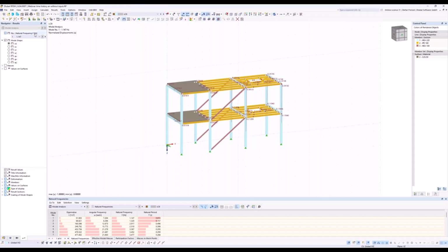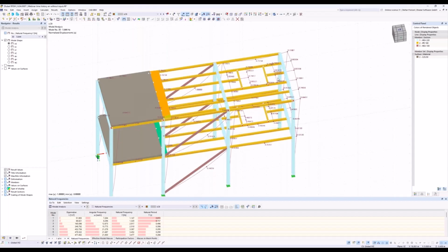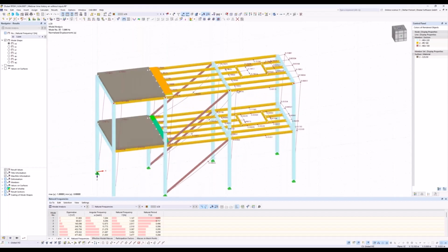So our first natural frequency you can find here in the navigator, or the result navigator. Here, of course, you can switch to the eigenvalues. And here is a really interesting eigenvalue. It's also 5.6 hertz, like our induced vibration, and you can see the structure will move in x direction globally. That's normally not so good when you get this. Yeah, because in this case, I will switch back to the